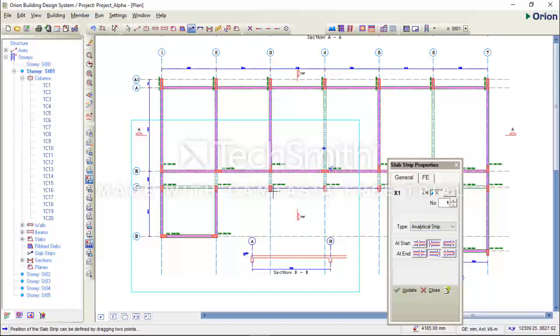If I'm drawing from a point where there is slab, at the start point, I'll click this button, the first one. If I'm drawing from a point where there is no beam, like at this region, I'll click the cantilever button. I'm going to explain this start and end option in my next tutorial properly to you. Thank you for watching the video.